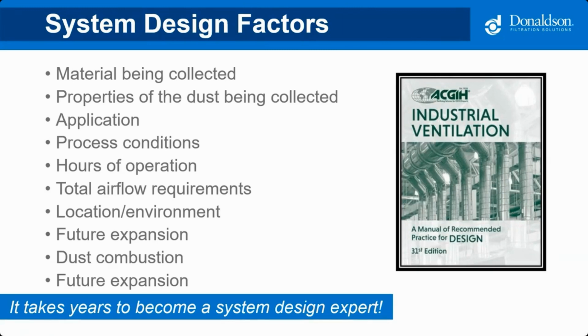Do they have compressed air available? Does the collector need to be located indoors or outdoors? Another, has the dust been tested for combustion and flammability? If it is, what NFPA standards apply? And finally, does the plant have expansion needs that we should consider when first designing the system? As you can see, there is a lot that goes into designing a system, probably more than most people realize.